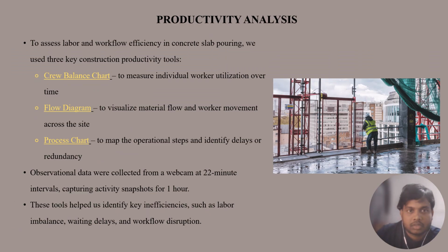This study evaluates labor workflow efficiency during concrete slab pouring. Three key productivity analysis tools were used. The first is the crew balance chart, which is used to assess individual worker engagement over time. The next is the flow diagram, to visualize the movement of materials and workers across the site. The third one is the process chart. It is used to map each step in the operation and detect delays and redundancies.